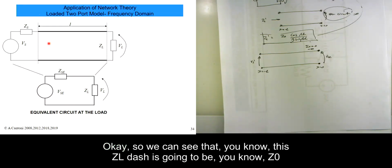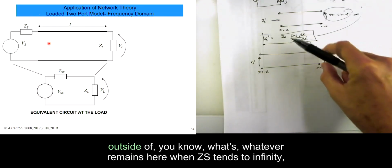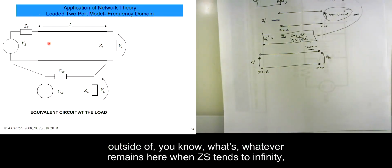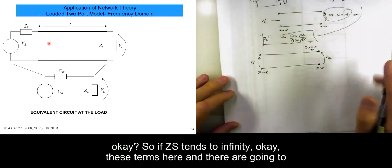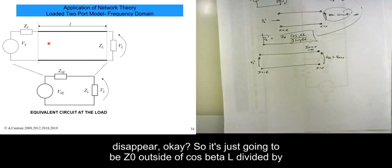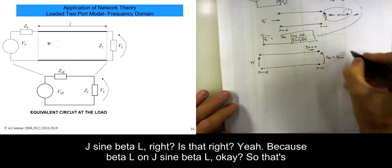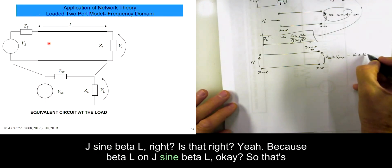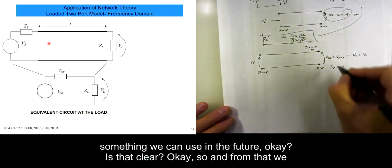Okay, so we can see that the ZL dash is going to be Z naught outside of whatever remains here when ZS tends to infinity. If ZS tends to infinity, these terms here and there are going to disappear. So it's just going to be Z naught outside of cos beta L divided by J sine beta L, cos beta L on J times sine beta L. So that's something we can use in the future. Is that clear?